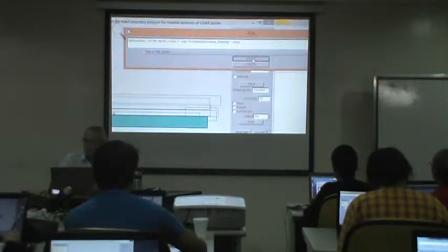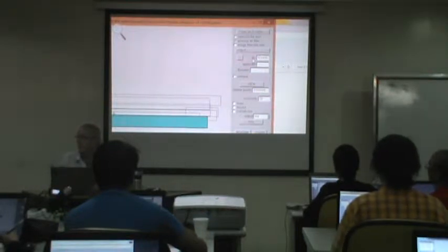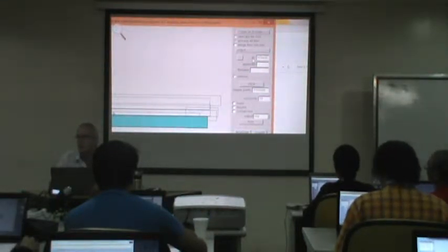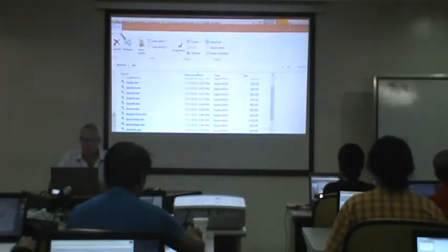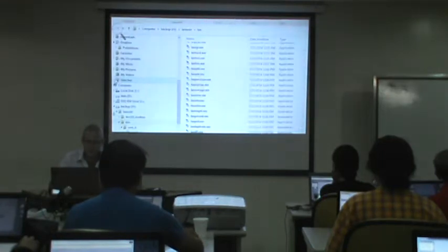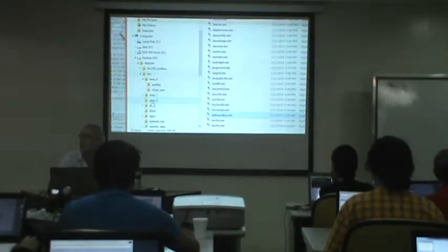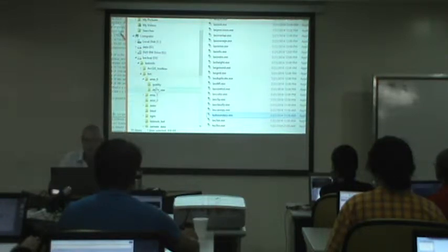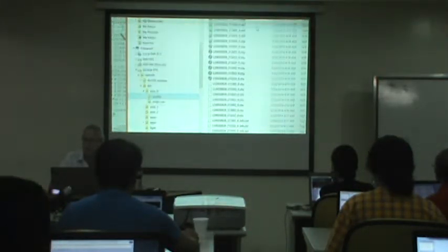Now on 7 cores in parallel on my machine, it was loading all these LAS files, doing the computation of the boundary, and putting them into the respective quality directory. If I go into that directory, I should have a lot of shapefiles now, in addition to the files we computed before. And here they are, the shapefiles.